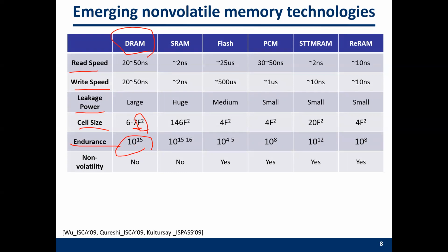If you have dead cells, how can the chip handle this? The answer is ECC. They will treat the dead cell as an error. Then by the ECC, you can still correct this error. Because you barely have one in a chip, the ECC overhead is not very large.